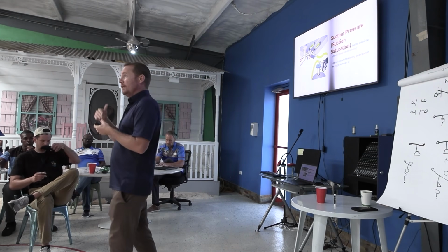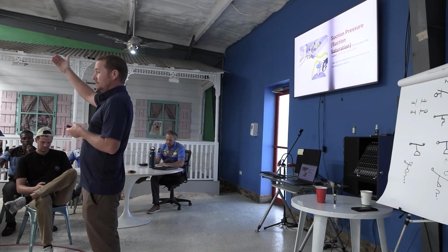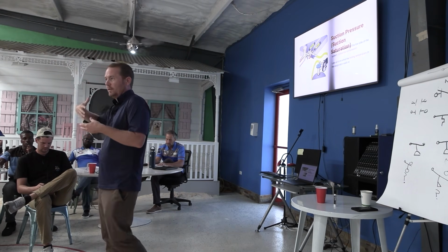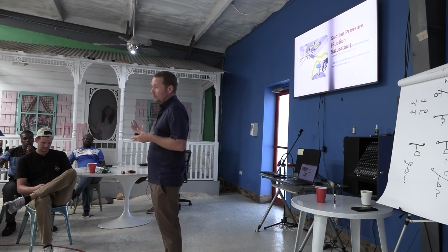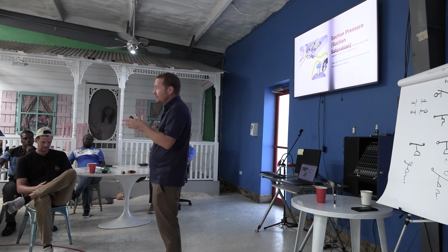So we have to keep it above 32. But we don't want to get it too high for obvious reasons, right? Obviously if the evaporator coil is too warm, it's not going to absorb heat. But in this market, we also don't want to get it too high because then it's not going to remove moisture very well, right? It's not going to pull moisture out. So we have to kind of do this dance.